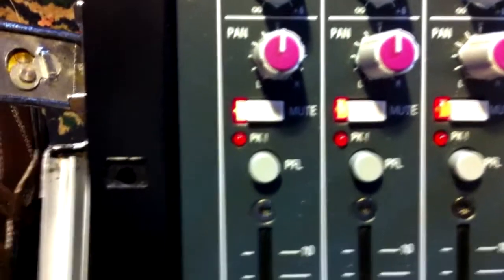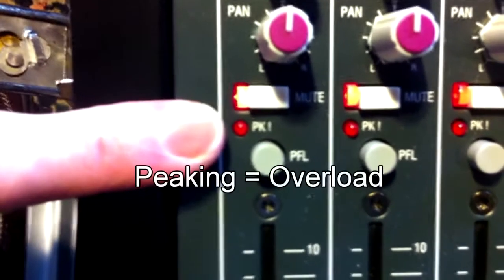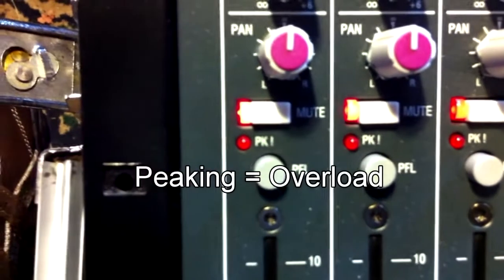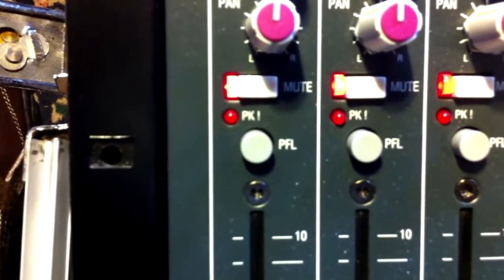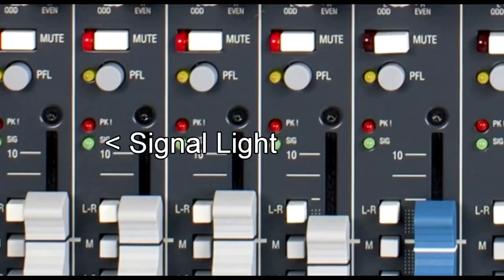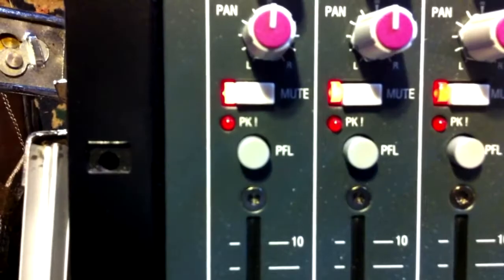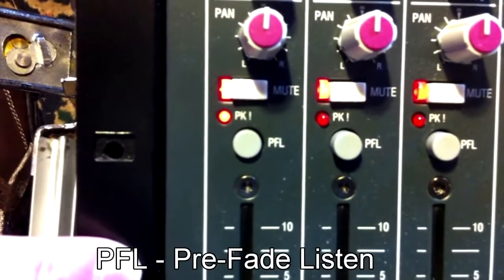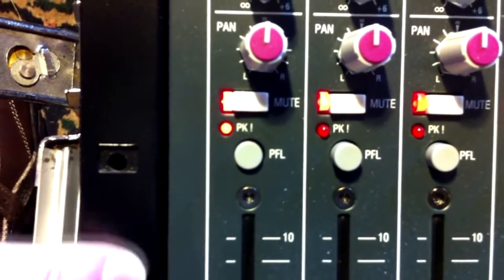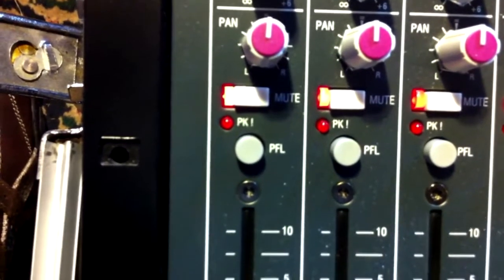Right under the mute button on this mixer is the peak indicator light. This will tell you if your signal is too loud and is punching the top of your max volume. Some mixers will also have a signal light, and this will tell you if the signal coming in through the channel is strong enough. Under the mute button is something called the PFL. The PFL stands for pre-fade listen, and you generally use that in metering, figuring out what your channel is doing before it hits the outputs.